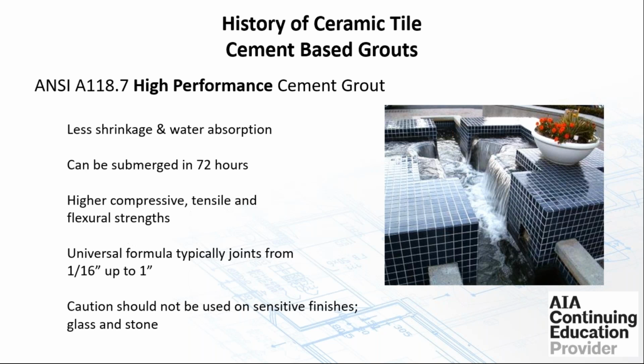It does have a higher compressive strength and tensile strength, also flexural strength. And we've seen the development of a universal formula to this that we can use anywhere from a 1/16 of an inch up to a 1-inch grout joint, and you won't have cracking or checking. So you don't have both a sanded and an unsanded.